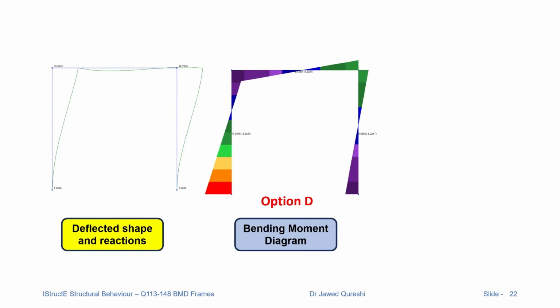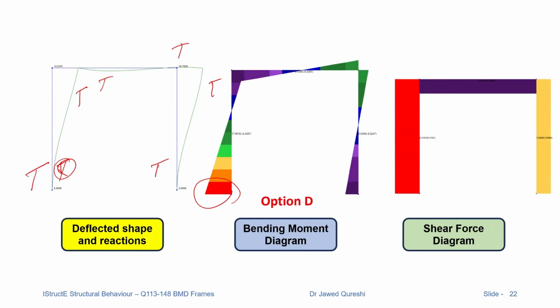Again, if I label it, we have tension here, tension and tension at bottom, tension at top, tension here, and then tension here. Sorry, we don't have tension here, we have tension at outside because we have fixed support. This is how we draw the bending moment diagram. We will have the direction of horizontal force leftwards, and remember that negatives are drawn inside, positives are drawn outside.